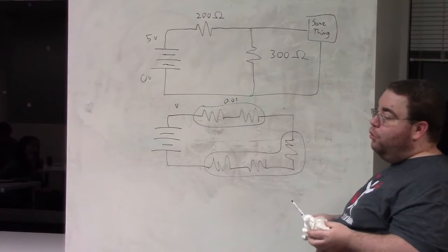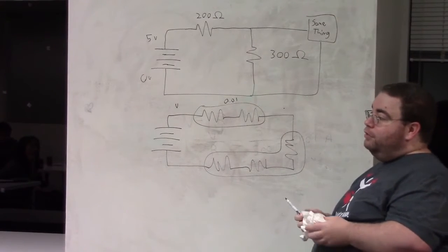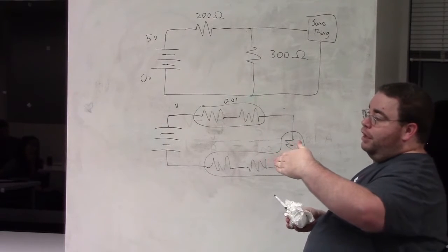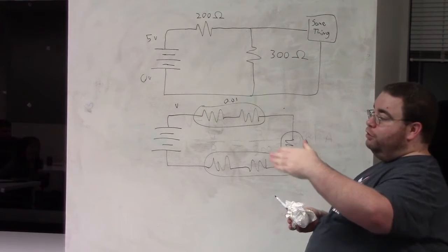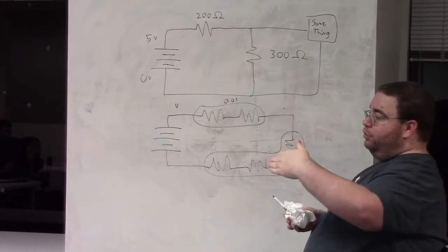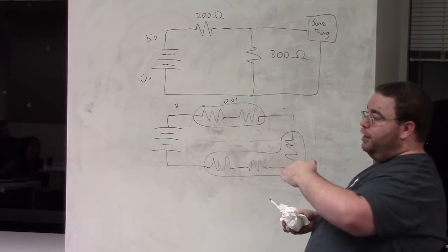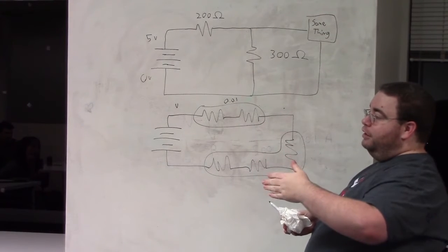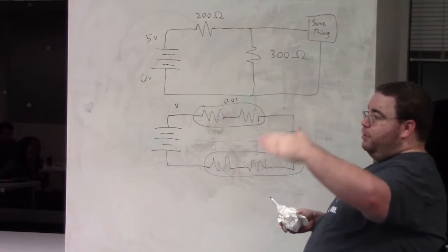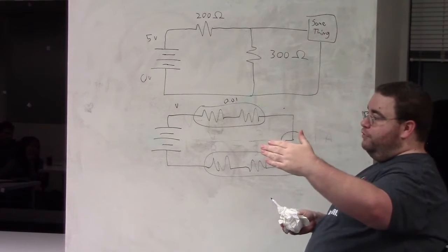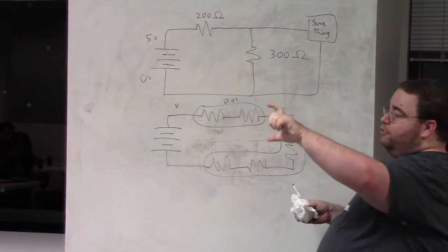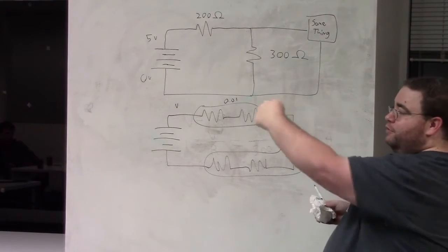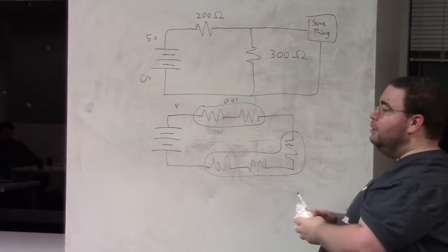diode. I don't want to get a whole lot into that yet, but a diode is a thing that will only send current one direction and block it the other direction. Most diodes have a breakdown voltage where, over a certain amount of backwards voltage, they will let it through anyway and then catch on fire. Zeners are special in that they will let it through anyway but not catch on fire. So if you have a Zener diode that's got a breakdown of like 3 volts, then you connect that backwards to ground with your 5 volt thing. Anything over 3 volts is going to go out through the Zener, the rest is going to go forward to your part. So it'll only let 3 volts through, that's it.